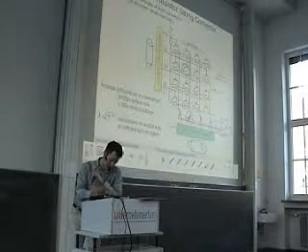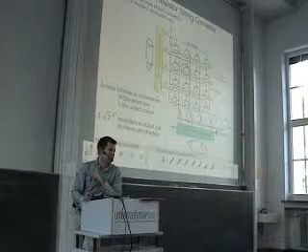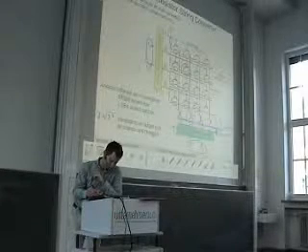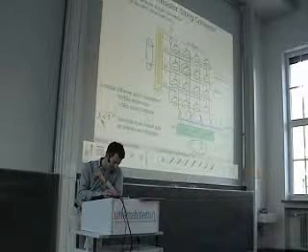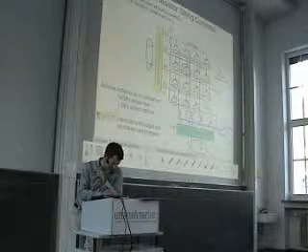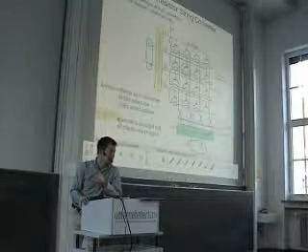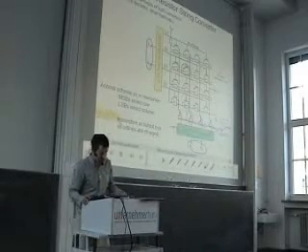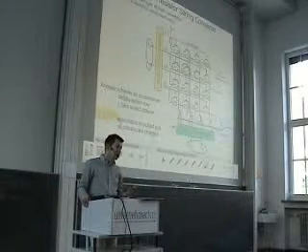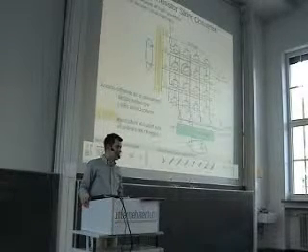Well, then we connected to this bus and we have another 4 devices. So we bring this down and have now only 2 times the square root of 2 to the power of n. And the square root is exactly this halving of the number of bits, 2 to the power of n over 2. So this reduces the effort not only for the decoders, but also reduces the parasitic cap that has to be recharged after the DAC is switched.